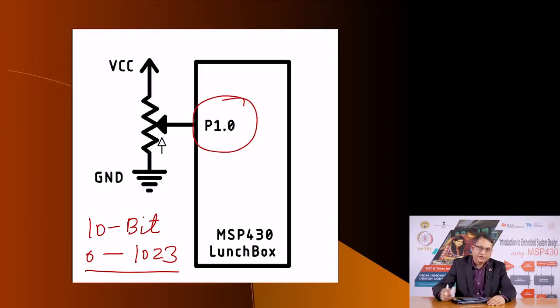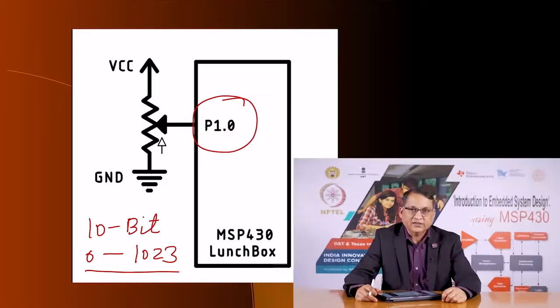Eventually, in the second variation of this program, we are going to display that number on our local display, which is a Charlie-plexed LED display. We have already covered Charlie-plexing in a previous exercise, so you are aware of what it is. This is a form of multiplexing which allows you to control a relatively large number of LEDs using a relatively smaller number of pins.